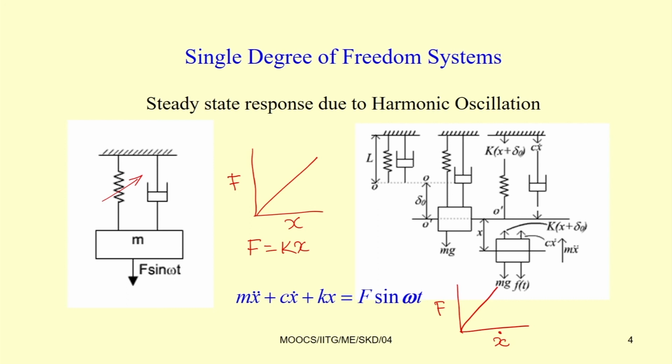Already I introduced to you two coordinate systems, one is the generalized coordinate system and the second one is the physical coordinate system. In the physical coordinate system, you can take a physical coordinate, for example from the support. Let L be the length of the unstressed spring and damper. Now by attaching this mass, there will be a displacement of delta 0. If you draw the free body diagram at this position, the weight mg is acting and the spring force is k delta 0. As there is no motion, C delta 0 dot will be equal to 0. So, mg will be equal to k delta 0.